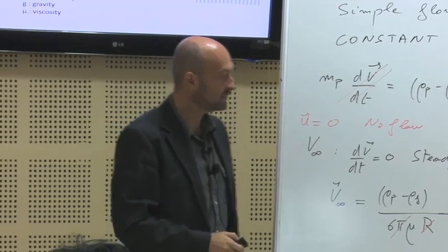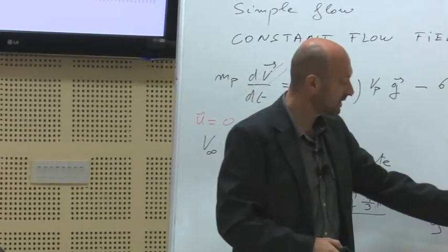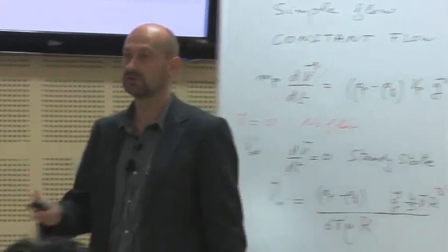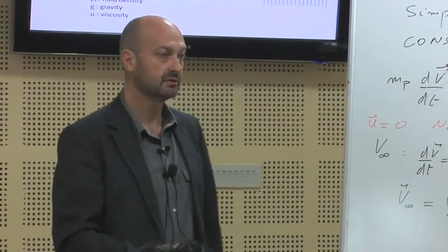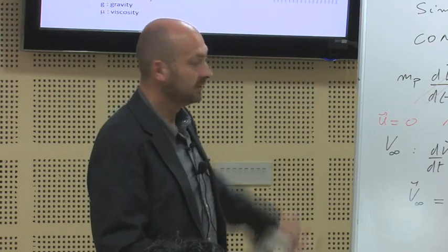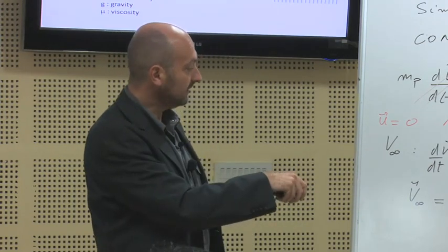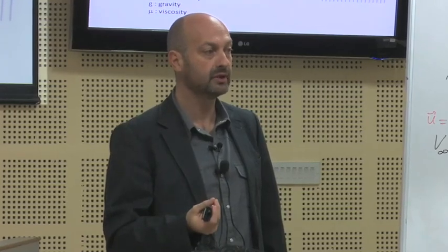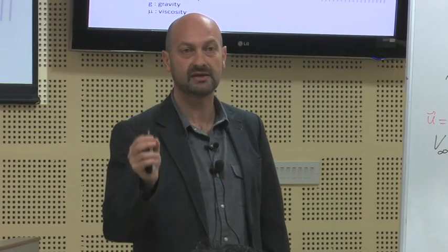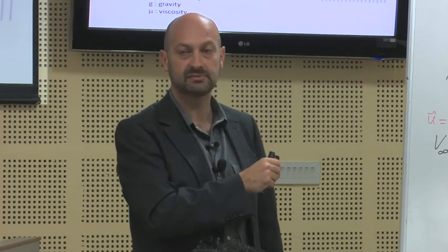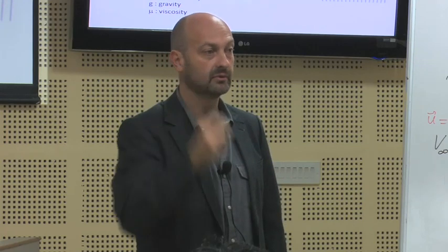But what is important is that it is proportional to r squared and inversely proportional to the viscosity. So if you increase the viscosity of your oil, for example, you will decrease the settling speed proportionally. But the radius squared is a strong constraint, because if you take a particle of certain size and divide the size by 10, you will decrease the settling speed by 100, 10 squared.